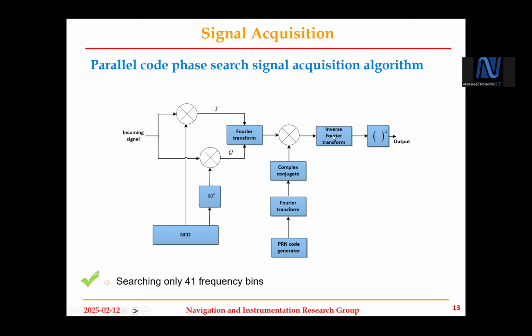When applying the inverse Fourier transformation here, because this is in time, right, it will give me an output in the time domain. That output here will be the shift in the code. Since I know the frequency I applied in the last search step, I'm looking for the delay on the code. So this will be the output of the inverse Fourier transformation. It is much faster, as you see, but again, applying Fourier transformation and the inverse Fourier transformation is a complicated or complex process.